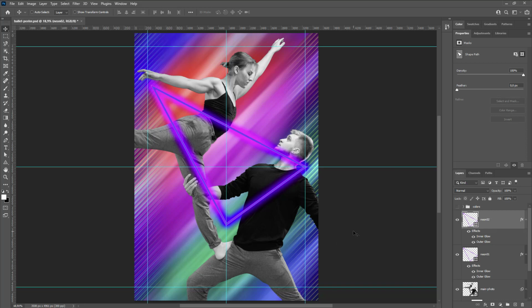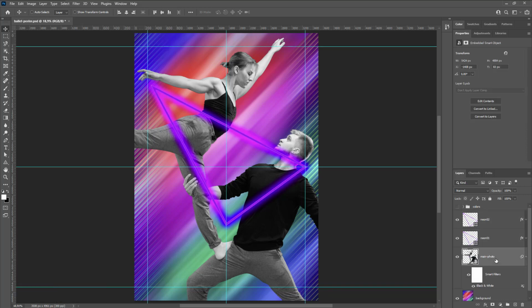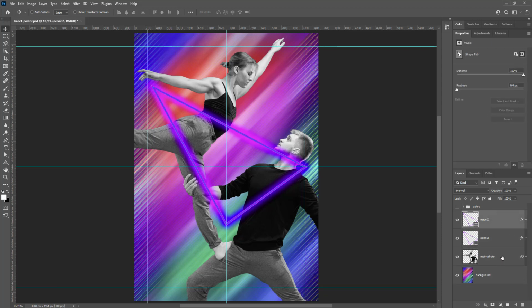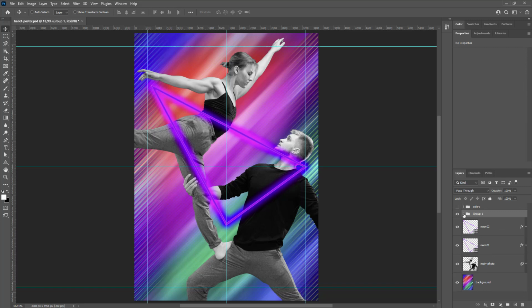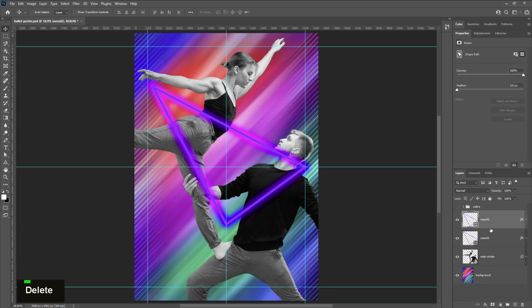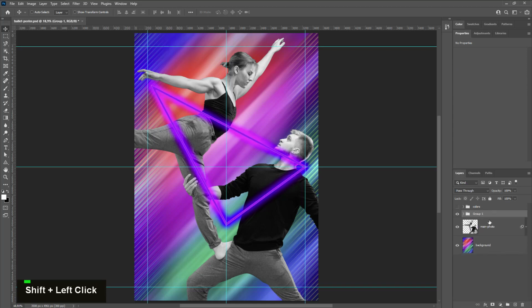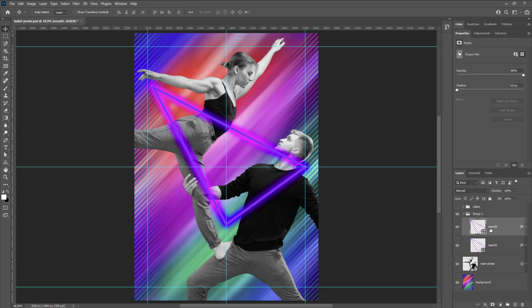So if you want to deal with multiple layers, and sometimes you have to hide multiple layers, the good thing to do is to probably select both layers and put those layers into a group, okay? And the way we usually do that is quite simple. So you can click here and you will create a new group. In this case, the group is empty, and you just have to click and drag and put your layers inside the group. Yeah, this is one way. Another way to do that is if you select both layers, you can click and drag and drop here on top of the folder, you know, and now you have a group and both layers are inside the group.